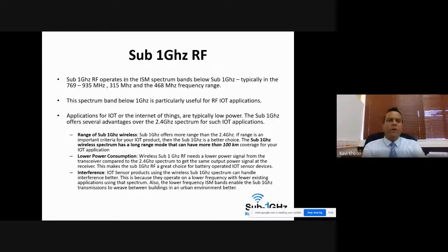In this case, I will have to transmit the sensor data itself. I'm not talking about the cloud, but a gateway which is quite far in terms of kilometers. You may have your sensors deployed in a city or whatever. You won't be able to make each of your sensors IP enabled where you are transmitting directly to the internet. So you will need to send it to some gateway, which will be quite far, and then the gateway communicates to the internet to transfer the data to a cloud platform. So we do require long distance communication as well.